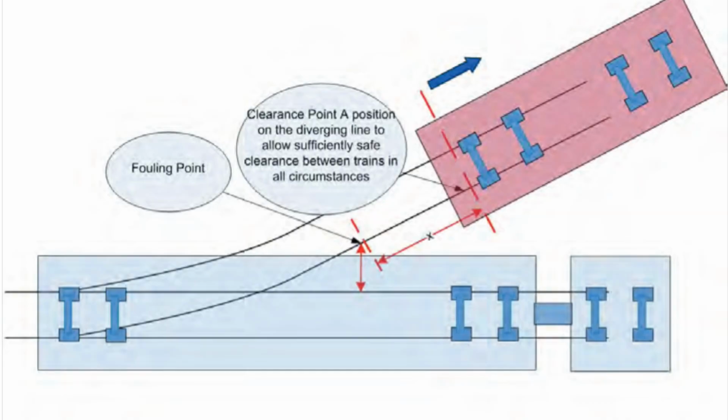And this really highlights the extreme precision required. When dealing with track-based train detection systems, engineers have to calculate clearance points with incredible accuracy. Take a look at junctions. The placement of insulated rail joints or axle counters actually has to account for the physical overhang of the train. That's the distance between the wheels and the absolute end of the vehicle.